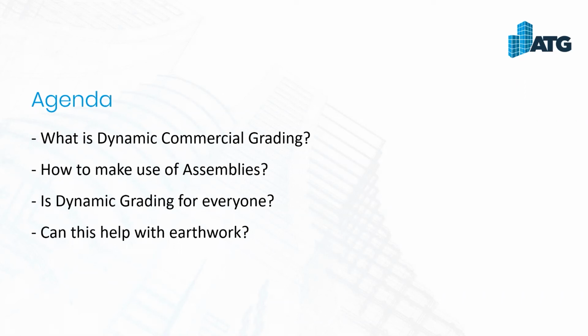And the way I came up with this is, can this help with earthwork? And that was my ultimate goal. So when I was doing the traditional design work, ultimately we want to have a balanced site or as close to balance as possible. And if you use a feature line workflow, you'd end up with way more feature lines than you anticipated. You'd have to drop your feature lines or copy your feature lines to another site and drop them